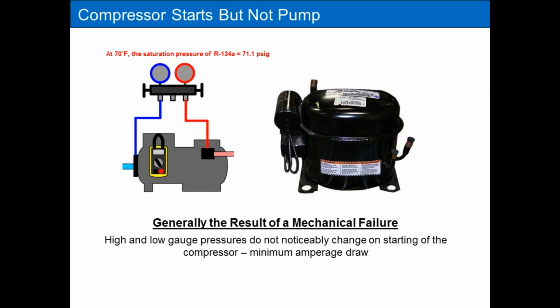When you do that, I'm going to recommend that you measure both your suction and your discharge pressures. A lot of guys just troubleshoot by looking at the suction pressure and not the discharge pressure, and that could lead you down a very dangerous approach. Your suction pressure is not the only thing you need to be looking at. If you want to troubleshoot these units properly, look at both suction and discharge pressures, and that will avoid you making some common mistakes that we'll talk about coming up.